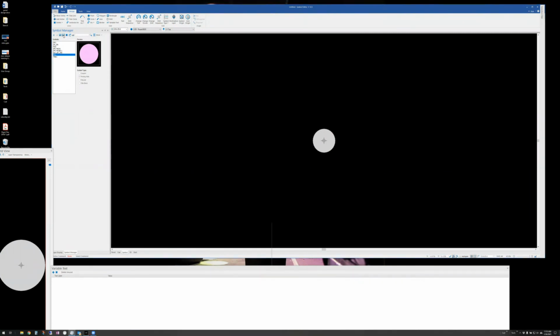So if I now go to save symbol as, it prompts me, I can either add a border around it so that when I do venting, it keeps it away, or I can just let it come all the way up to it by doing a save data as. Okay, then I give it a name. Now, this is kind of old school in that these names can't have spaces in them, so kind of silly, but they can't. So we're just going to call this FID1, and we're going to save it as a fiducial and click OK.